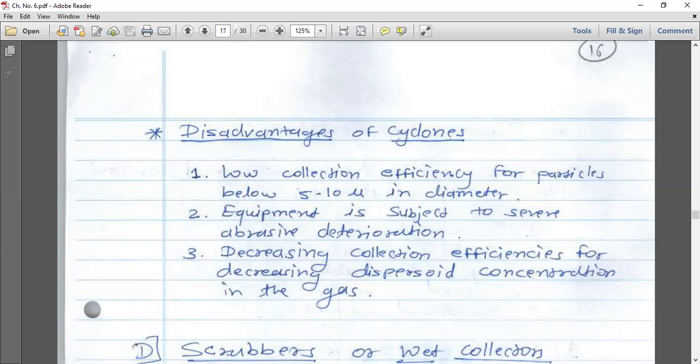The way we saw in water supply engineering or wastewater engineering, after the removal of bulk material in a primary treatment process, we go for secondary, so we are arranging sequences for fine treatment. Same here for gas pollution removal. First you can go for the settling chamber, then the cyclone separator. It depends upon what type of treatment you wish to give. If you want to remove the air pollutants at a certain percentage, you can decide how many equipments you need to arrange in a series.